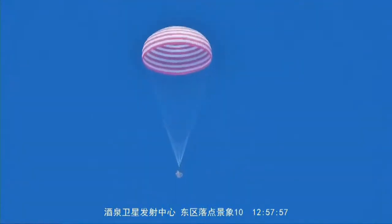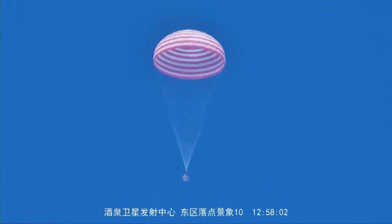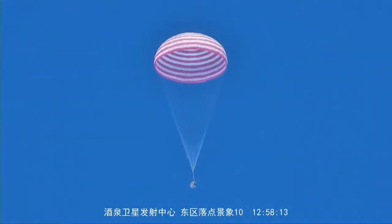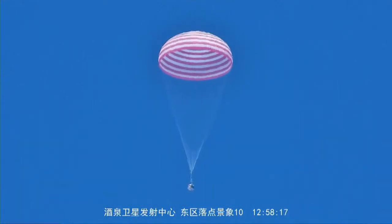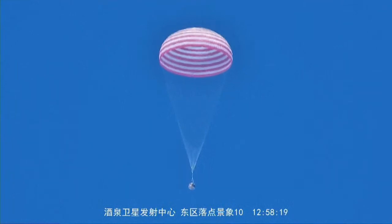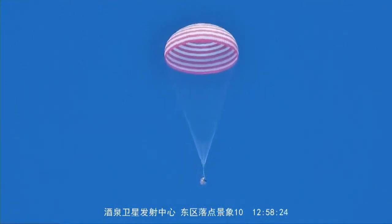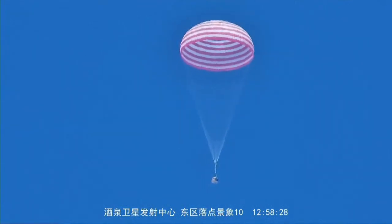No, this is the heating shield, the main heating shield. It jettisons the main heating shield. Right. Because, as Professor Zhang has already mentioned, we need 4 solid rocket motors to continuously slow down the vehicle at touchdown. Now the heat shield is gone, right? So that signals the landing is quite imminent. Exactly. So as to expose the 4 rocket motors. And even with this huge parachute, it's still too fast at touchdown. That is the reason why we need 4 retro rockets.